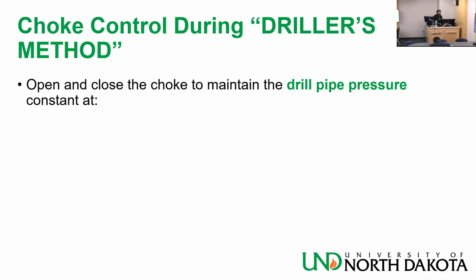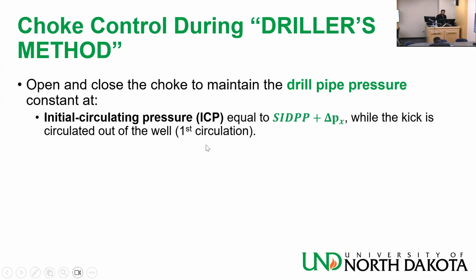So in real life, don't move the choke too fast. Wait to see the response, make sure the response is proper, and then open it more or close it more. Yeah, that's a very good point, actually. So, any other questions?